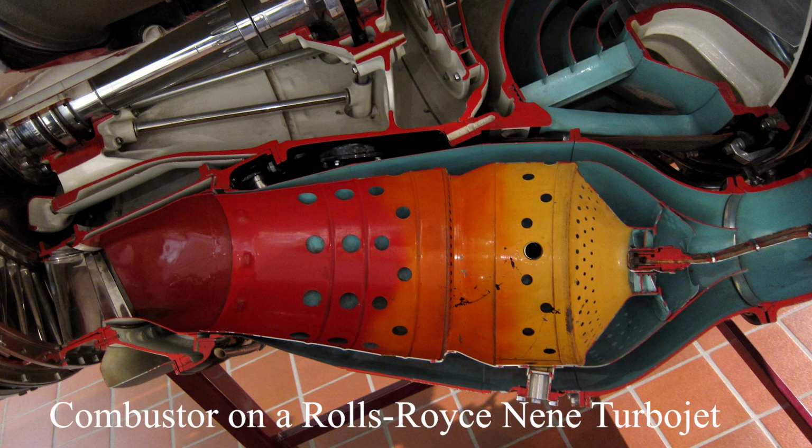If there are hot spots in the exit flow, the turbine may be subjected to thermal stress or other types of damage. Similarly, the temperature profile within the combustor should avoid hot spots, as those can damage or destroy a combustor from the inside. The combustor should have small physical size and weight. Space and weight are at a premium in aircraft applications, so a well-designed combustor strives to be compact. Non-aircraft applications, like power-generating gas turbines, are not as constrained by this factor.